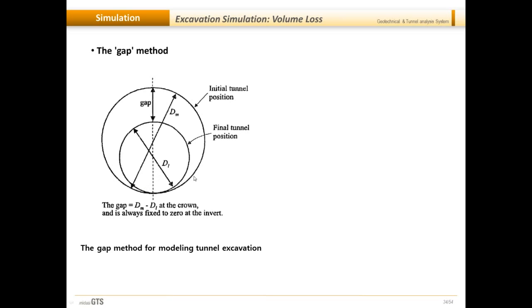And depending upon what construction methodology you are using, the void size and the diameter or the initial position of the excavation would vary. If you are using TBM, then you can have more control over this opening size. But if it is some other construction method, then you cannot really control the size that much. So engineers go for a bigger diameter so that they can accommodate for the workmanship and account for the misalignment of the tunnel machines and all that.